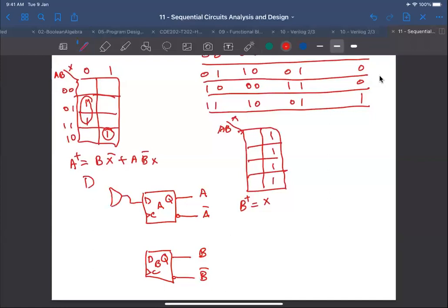And we have two ANDs here, one with B X complement, and the other one is A B complement X. And for B, it's only X. CLK, CLK. It's the same clock signal. You just have the same net, so there is an implied connection between the two nets. And then my Y is A and B, just A AND B. This is my Y.